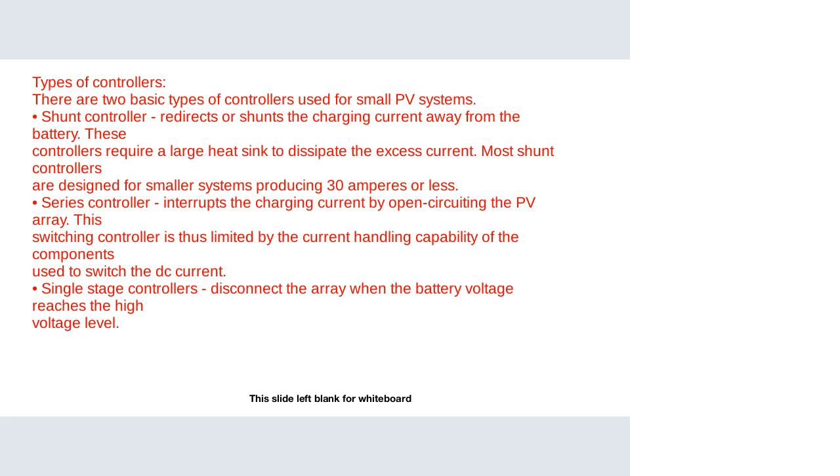And then the opposite of that is the multi-stage controller. This one basically does almost the opposite of what a single stage controller does. It allows different charging currents as the battery nears full state of charge. This technique usually provides a more efficient method of charging the battery. It is more efficient as compared to the single stage controllers.